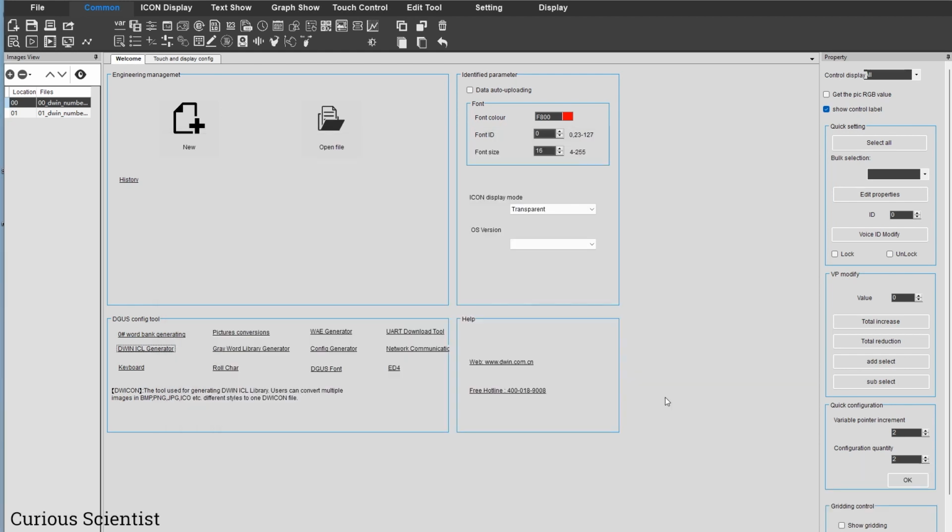So now you know everything about generating fonts, generating the page file, the package file for it, and generating the config file for the display. And you also know how to format the SD card that you will use to upload the code to the display. So now I can show you the coding part or assembling the display part.